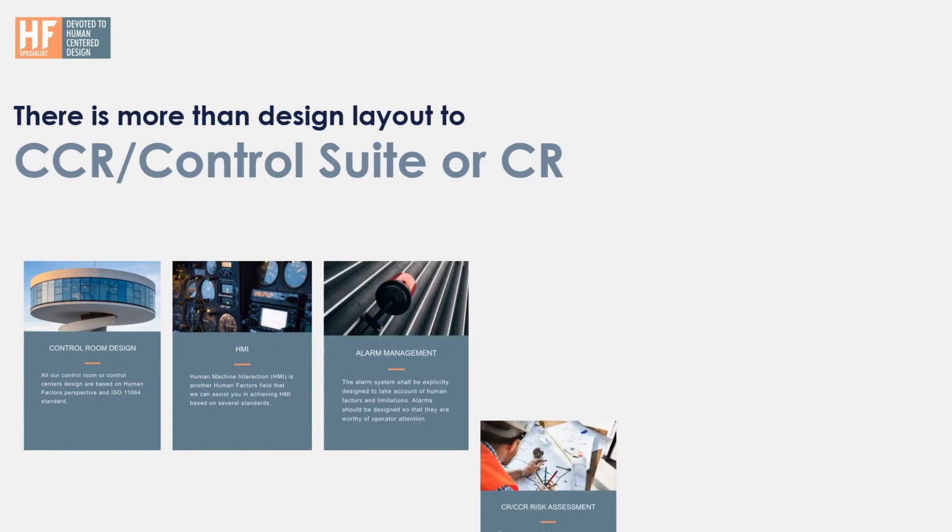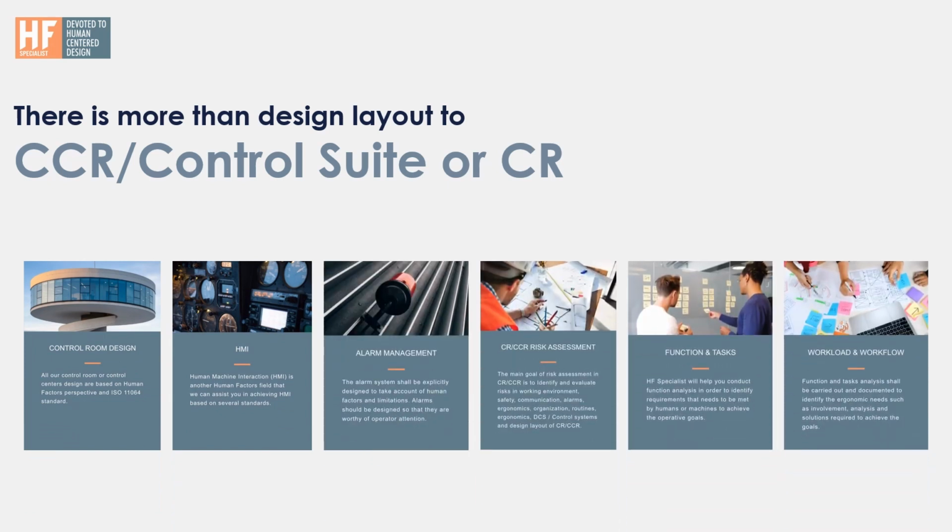One thing that you should think about, as I said earlier in the beginning, is that I have often seen industrial companies focusing on the control room design, which is very good, but control room design should be the end of the process, not the beginning. Some companies have done it and they end up with a beautiful control room, but beautiful is not always functional. And you have to keep in mind that there is more to control room solutions than only control room design. You have HMI, you have alarm management, you have risk assessment. If you identify the functions that are fulfilled with the risks, then you have to do a risk assessment and see the impact of it. You have to perform function and task analysis, see the workload and workflow, and so on and so forth. So don't end up just doing a control room design.